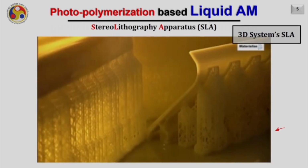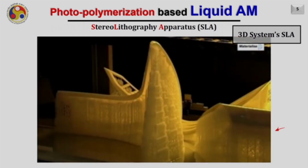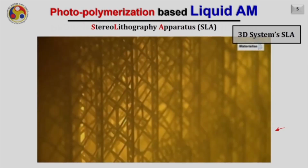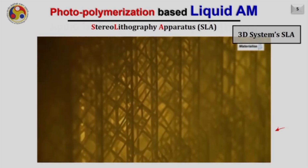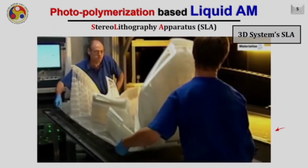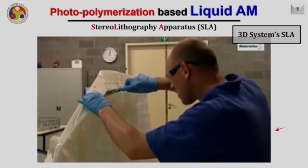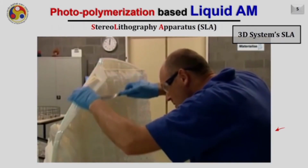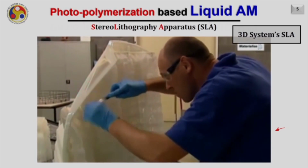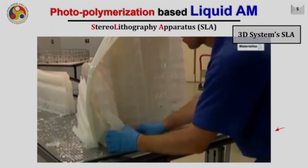To get the final shape, these support structures have to be removed by using appropriate tools such as knives, chisels and so on. Removing support material is a very difficult task, particularly in SLA. The worker has to be very careful because he should not damage the main material cured here while removing the support.